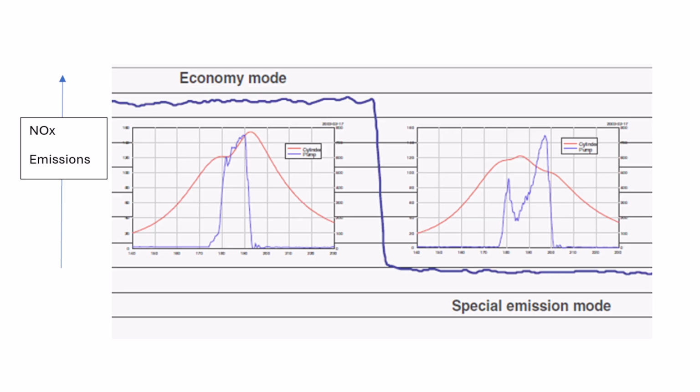In emission control mode, what is done? Maybe injection is done twice in a cycle. For the test cylinder, it is part injection and then once again injection. So the peak pressure is reduced. Peak pressure reduced, that is how the NOx emissions are reduced.